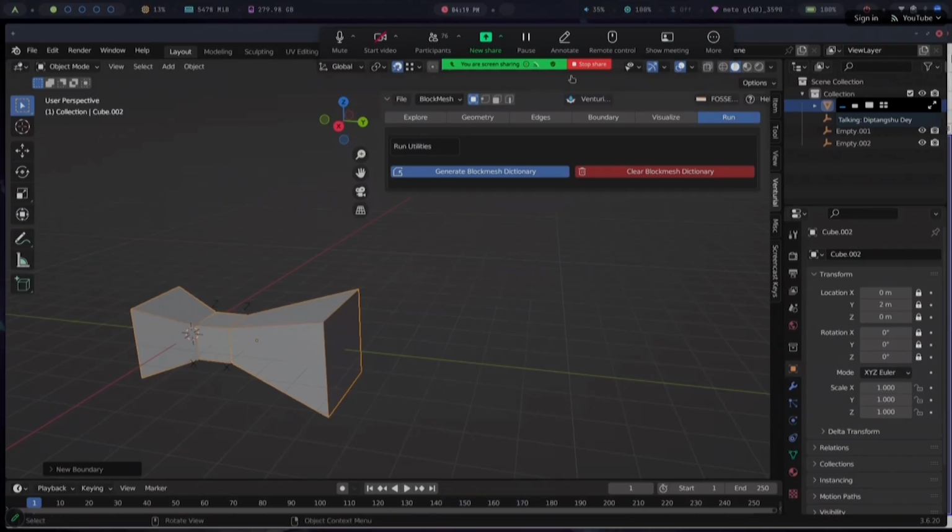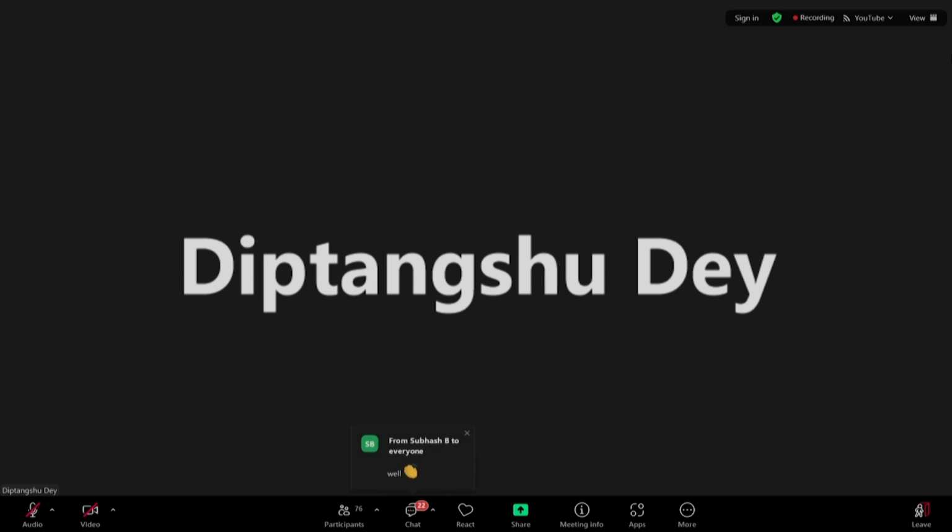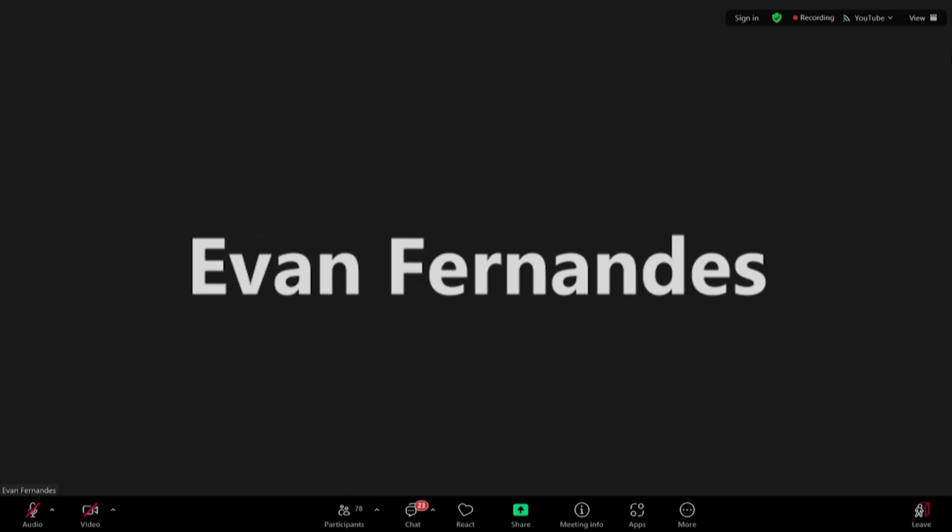And if anybody has any questions, they are welcome to ask in the chat box. There's one question that says how to use Fluent mesh in OpenFOAM. Quickly I'll just show that. There is one command. I'm typing it in the chat for everyone to see. You can use the command fluent3DMeshToFoam, and then you type in whatever mesh file you've created, the .msh file. So in this one, I'll type here filename.msh.